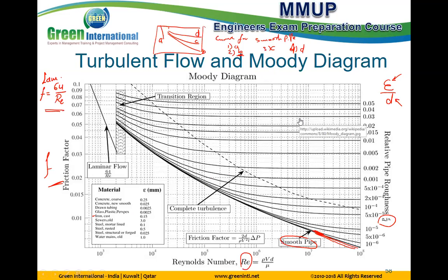Sir, about this laminar flow, how do we know laminar and turbulence? Laminar is for the curve A, and the range goes up to 2,300 Reynolds number. Then turbulent starts from 4,000. In between is the transient, this area, as you see, a small area here.